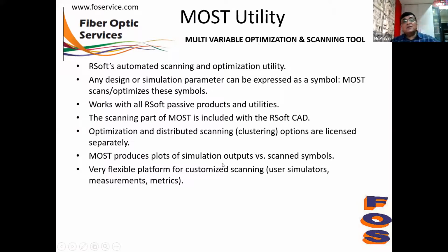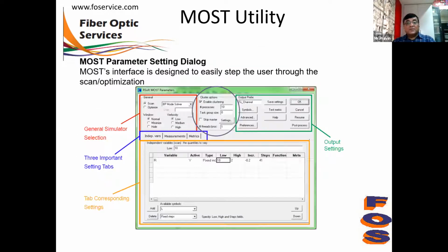Next is the multi-variable optimization and scanning tool that's called MOST. This is a very unique tool available from the RSoft device tool. Here you can scan on multiple variables and automate your process of simulation to find out how the device performs at various parameter values.